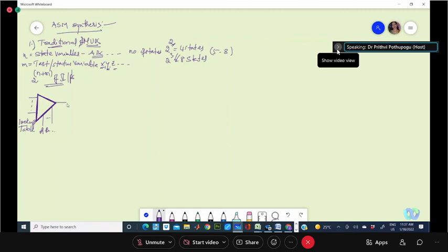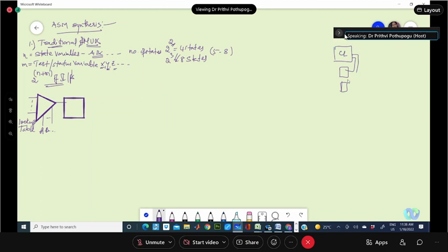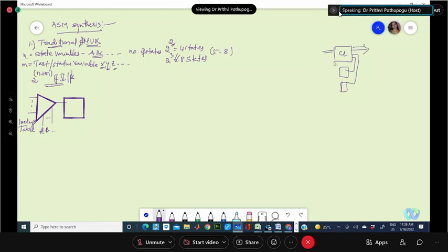And how many muxes should be used relates to how many states you have. Okay, that means say you have 4 states, and you are taking 2 state variables, meaning each state variable will be using one flip-flop. Yes or no? If this is the setup of the design we take, each variable will be taking one flip-flop.